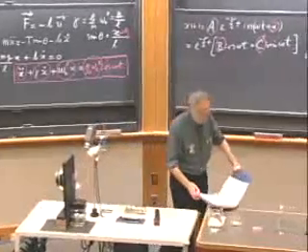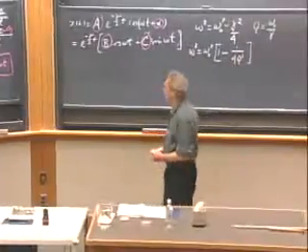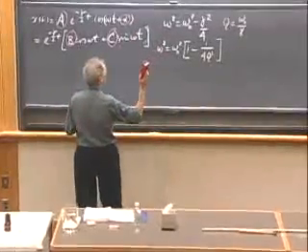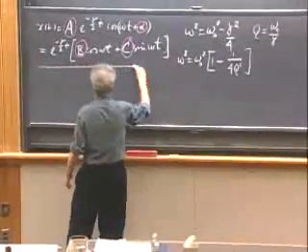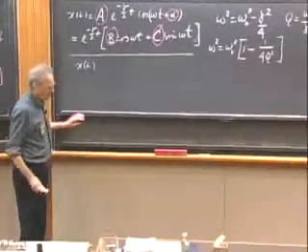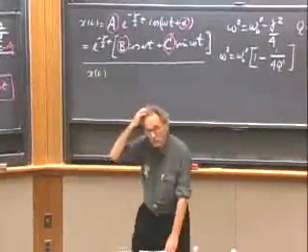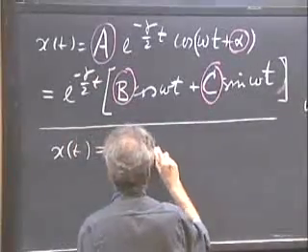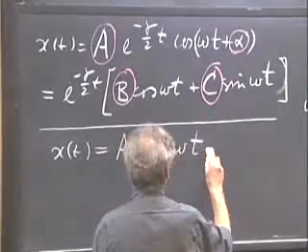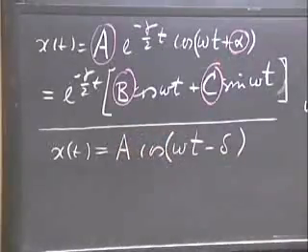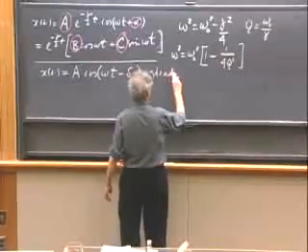Now the solutions, that's a different story. That is something that I wouldn't want you to derive either, but the solutions now become as follows. I now get x as a function of t is an amplitude, which is a very strong function of omega, but I will simply write it down as an amplitude A, times the cosine of omega t minus some phase angle delta. And this is what we call the steady state solution. Steady state.